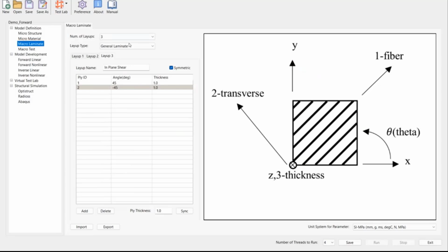But for sure, if you would like to add a laminate, you can do it. You simply increase the number here. If I want to, for example, create a symmetric quasi-iso, I could do 0, 45, 90, minus 45. Let's use a ply thickness 0.5. Didn't do it. Need to check that. Okay. Ply thickness.